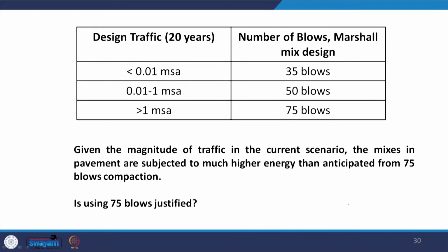This table which you are now seeing gives the number of blows for different levels of traffic in case of Marshall mix design. You see that if the traffic is less than 0.01 MSA, you have to prepare a mixture with 35 blows.